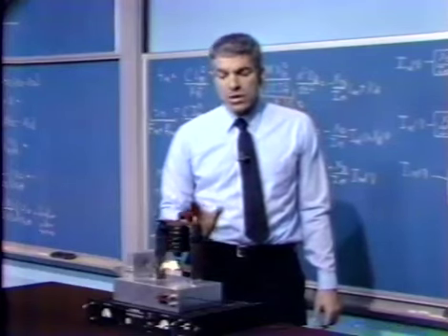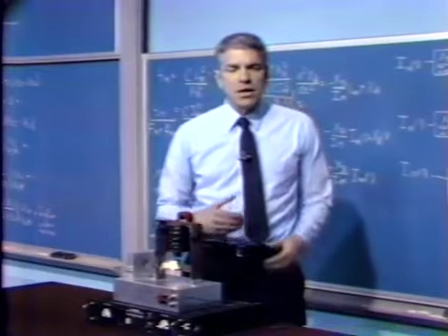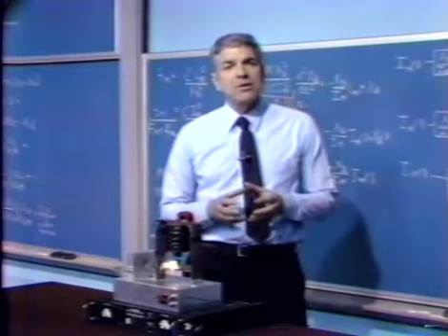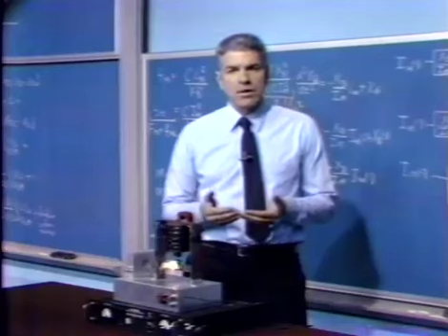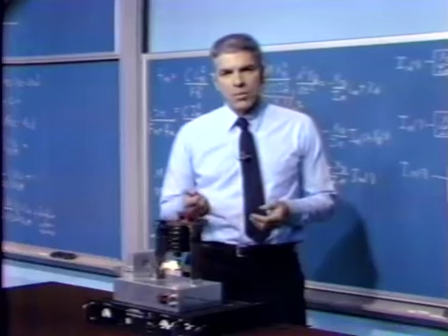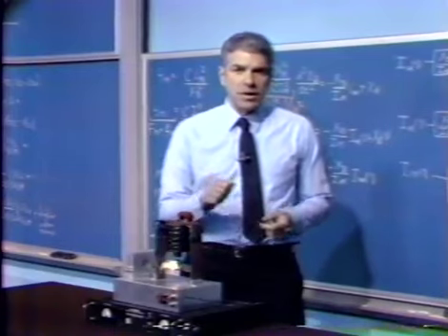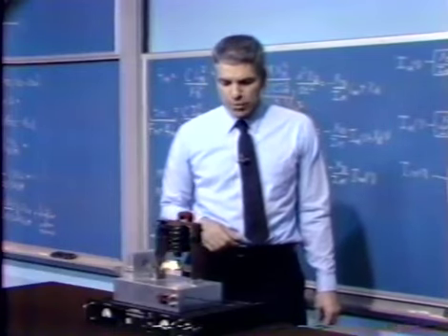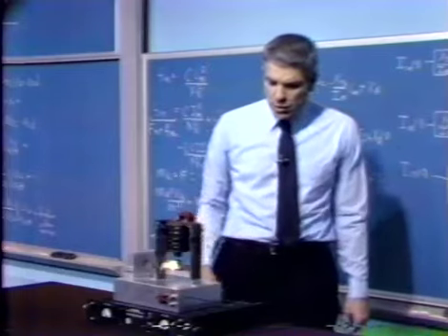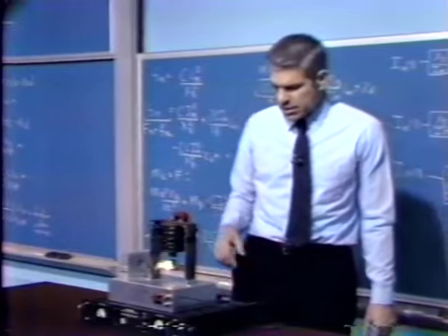Once we're to that point, we get it stable in an absolute sense. The rest of the sort of quote optimization goes very, very quickly because we can now look at a transient for the system and we can see the effect on the transient of adjusting A naught, of adjusting zero location, very rapidly improve the performance of the system that way. And that's exactly the way I did design the system.